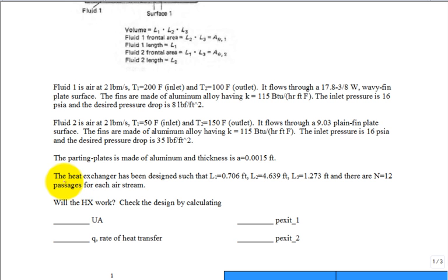You're saying, hold it, you told me the inlet and outlet. Well, don't calculate it from the m dot C sub P delta T of the two streams. Calculate it as if it's a heat exchanger, knowing only T in of the hot and T in of the cold, and you calculate how big it is thermally, UA, right? And then it's a cross-flow heat exchanger, so you can use the effectiveness-NTU method. And then calculate that exit pressure.